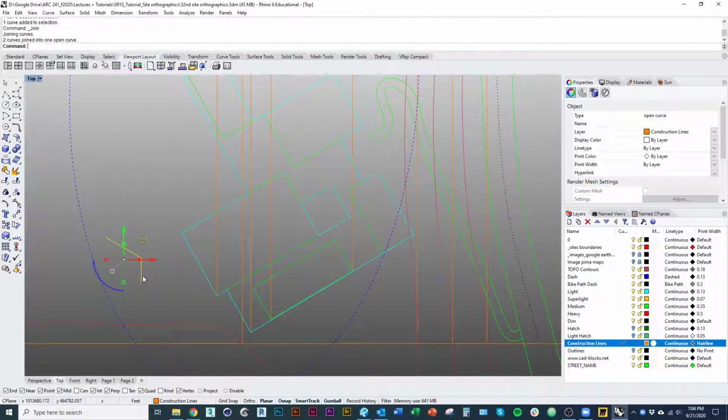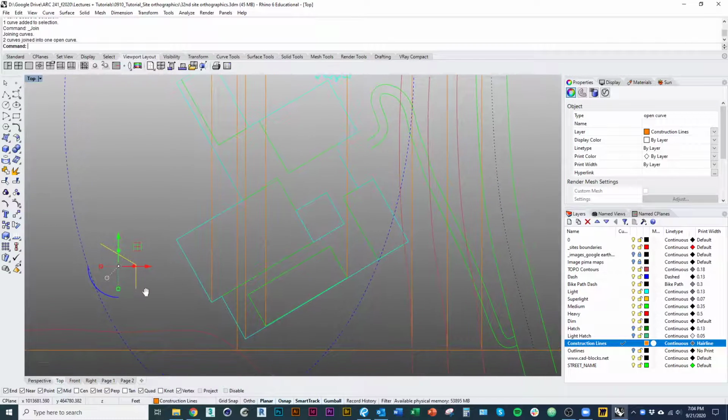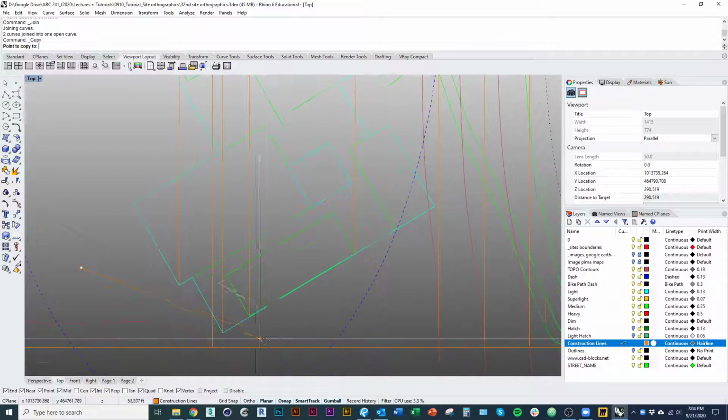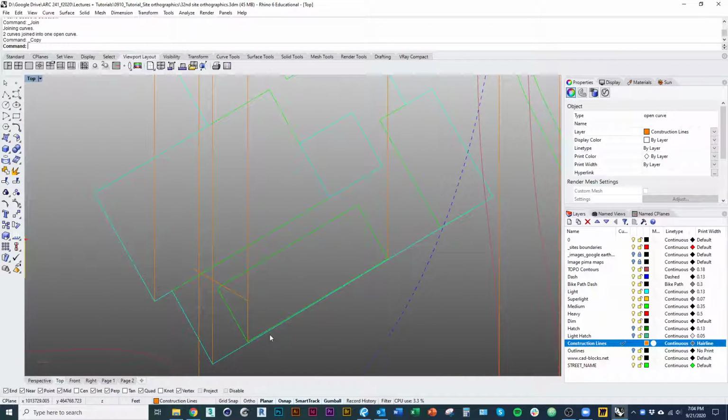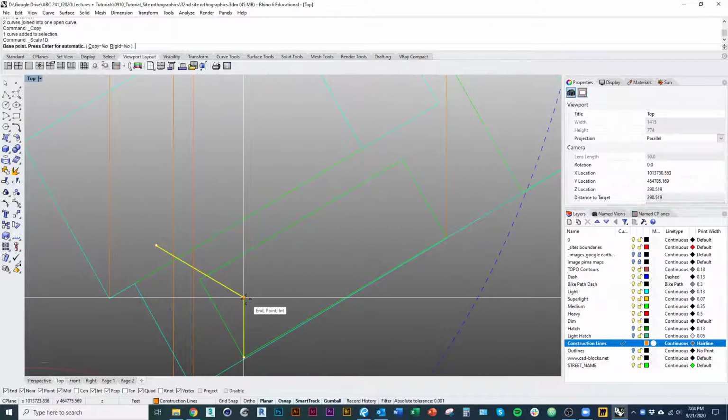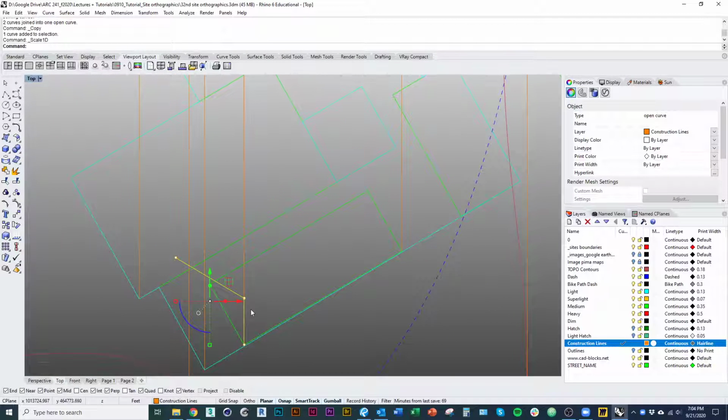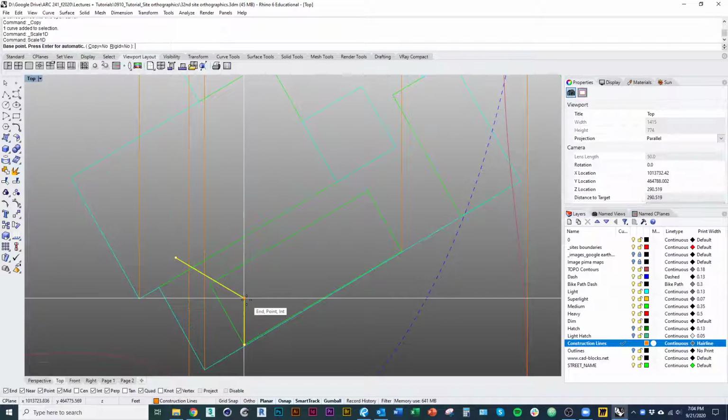To make my life easy, I'm actually just going to copy it each time I want to use it to show what my roof will look like. So I selected it, I lined it up to one corner. I'm going to scale 1D it, holding Shift, and then I'm holding Tab. Snap to the other end.